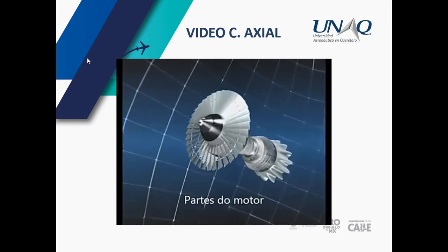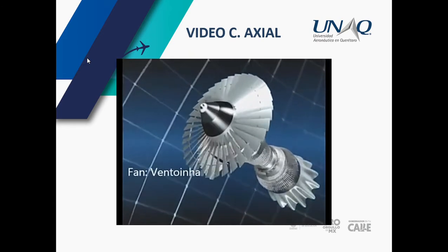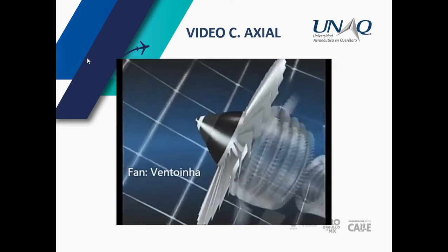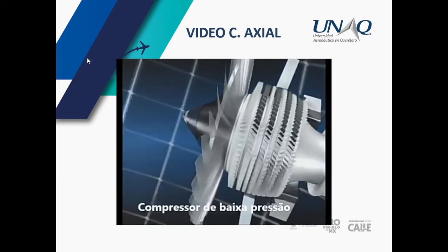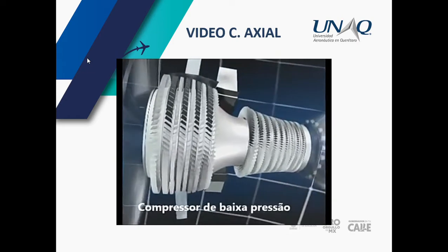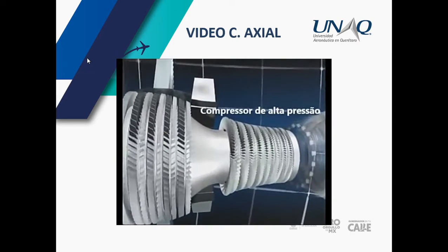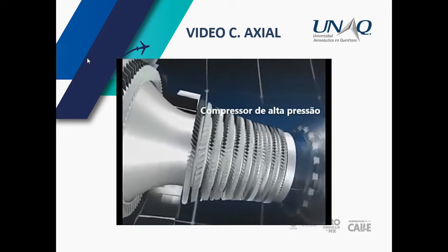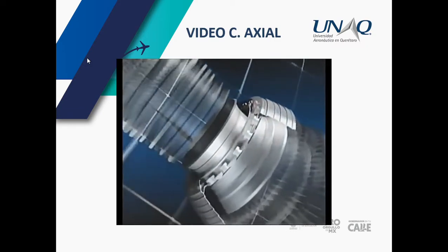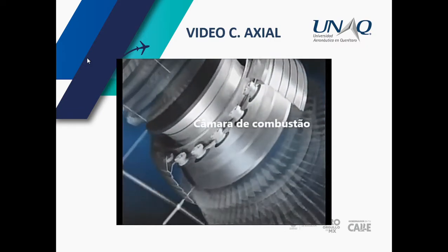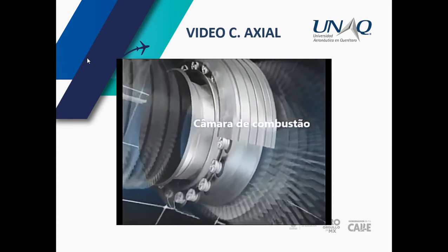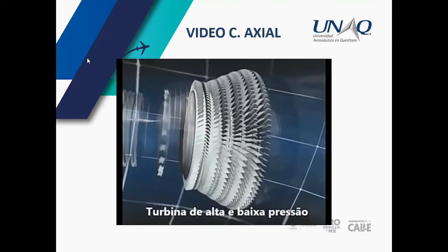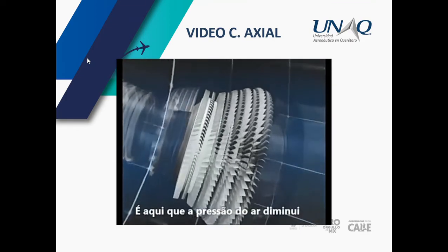These are the various components of the CFM56. The fan, which is a large diameter propeller; the low and high pressure compressors with 13 stages, which step by step increase the pressure of the air as it flows through them; the combustion chamber, in which jet fuel is mixed with air and burnt; the high and low pressure turbines, in which the pressure of the hot gas is reduced as they drive the compressors and fan.